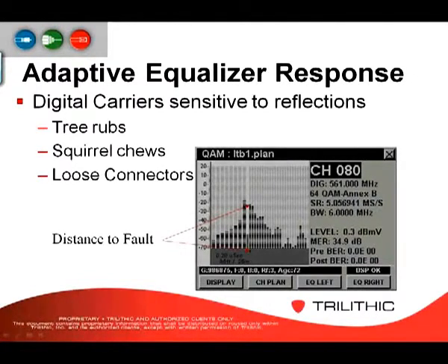Now, the adaptive equalizer changes the level at a particular time. It's time-based. This time matches the time at which the reflection occurs. The gain is reduced only at this time, thus reducing the reflection. So the thing is, even by looking at the drawing, you can see how it looks like a little stair step, and that's based off of the amplitude or the level of the reflection or signal that's reflecting back at that particular time interval,